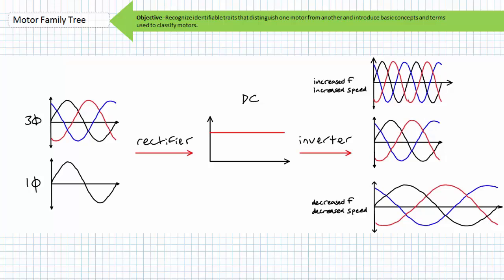The motor drive isn't really part of the motor, however, it's essential to governing its torque and rotational speed performance. The inversion half of the power electronics inside a motor drive are essentially what does the conversion of DC input to multi-phase AC for a brushless DC motor.